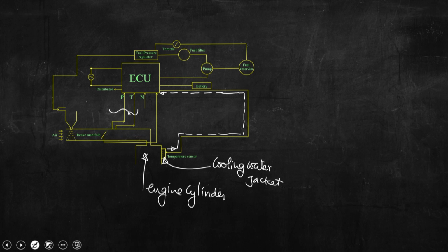So, this pressure and temperature, you can see these are the inputs, because these are directly related to the mass flow rate of incoming air. These pressure and temperature sensors are connected to the intake manifold. Also, this is a sensor which is used to control the throttle opening area, the throttle valve adjustment, and this is another sensor which controls the speed of the engine. This is N.